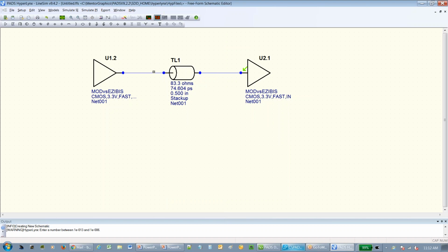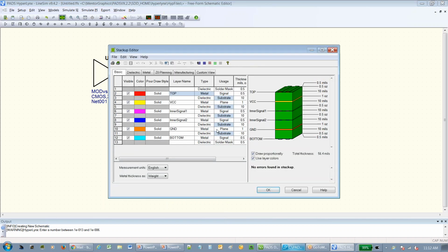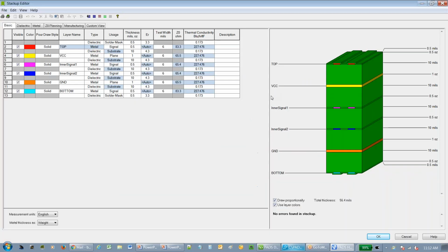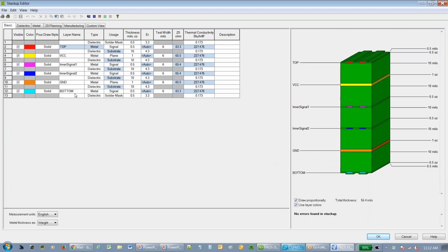Okay. All right. So that was just a real quick example. Let's play around with the stack-up stuff a little bit. As I mentioned in here, there's a lot of things you can do with your stack-up, more than just doing a quick impedance check with a calculator online. So in here, again, things are very important when it comes to the solder mask, the material you're using, how thick it is, the dielectric constant.